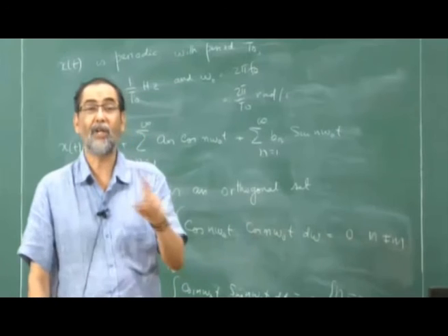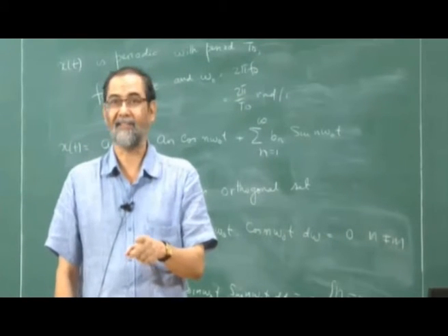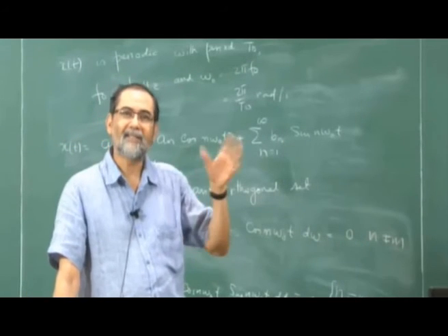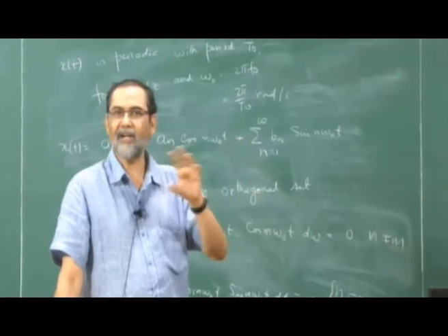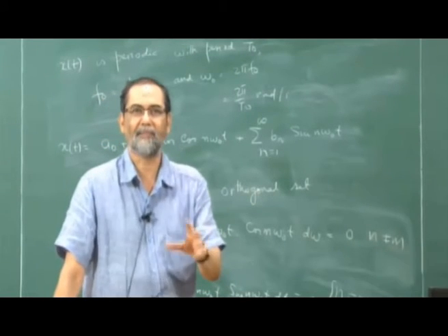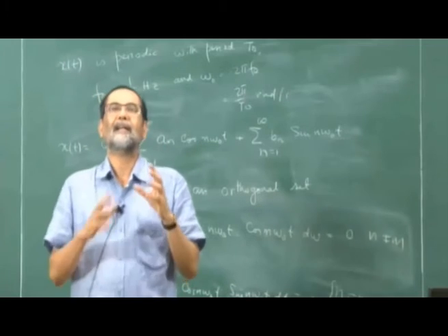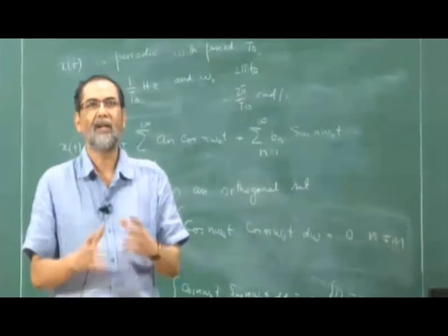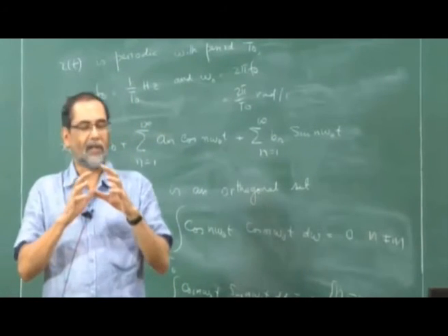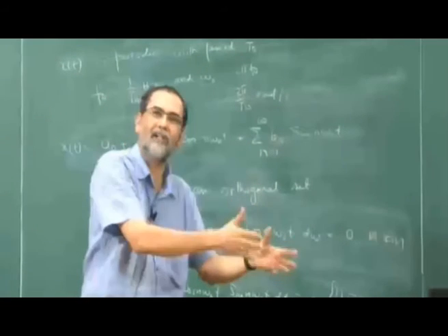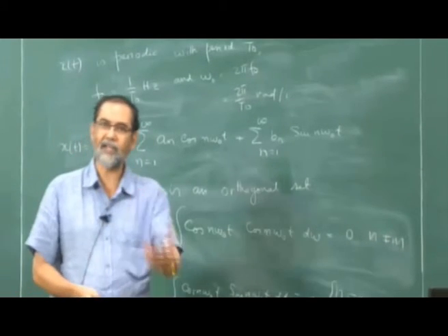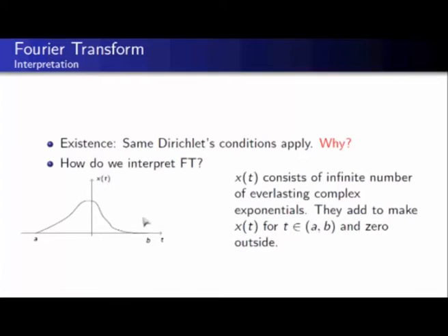By that definition, u of t is not an energy signal. If we write a Fourier transform for u of t, it is by doing some tricks. Straightforwardly, you cannot write a Fourier transform for signals like u of t. Please understand this difference very clearly. This is something that mathematicians always warn us, and we don't get that warning often, so heed this warning. The Fourier transform does not exist for signals like u of t if you strictly go by the Dirichlet conditions. After another 10 minutes I'll make another stop and maybe we can have more discussions.